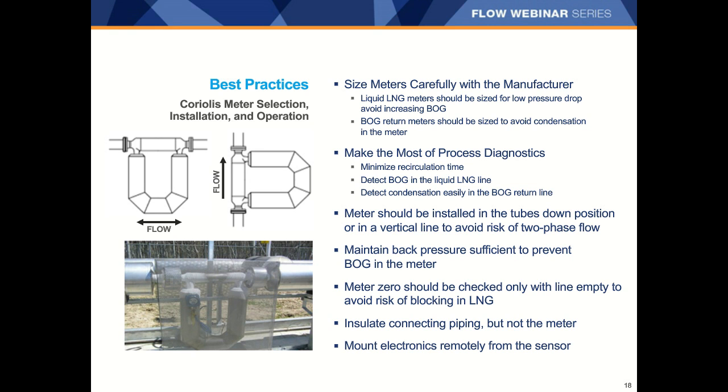Because LNG is so cold, we recommend mounting the meter electronics away from the meter to avoid making the electronics cold unnecessarily. Because we offer meters that can be ordered with the electronics mounted directly on the meter or remotely, we can make this a simple choice with Micro Motion Coriolis meters.